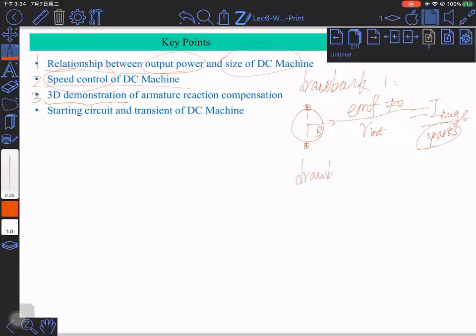Today we are going to introduce the second drawback. Drawback 2. What is it? It's called unwanted flux field weakening. Some people are also calling this flux weakening. We have to say that in AC machines, field weakening is wanted because that's how you obtain a higher speed upper limit for AC machines.